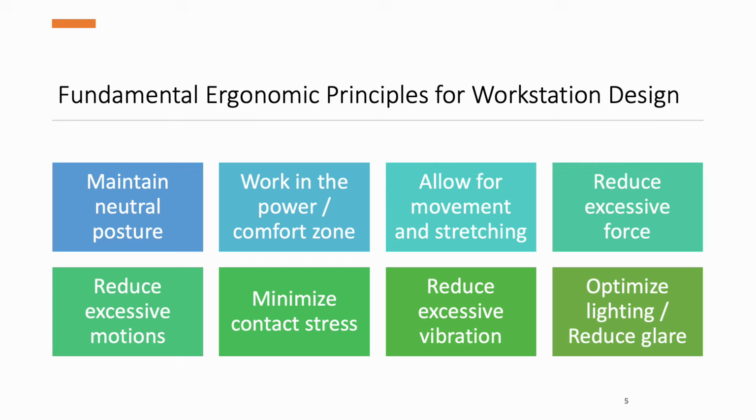When it comes to workstation design, there are 8 fundamental ergonomic principles, including maintaining neutral posture, working in the power or comfort zone, allowing for movement and stretching, reducing excessive force and motions, minimizing contact stress, reducing excessive vibration, and optimizing lighting and reducing glare. We will go over how we can achieve this in the following slides.